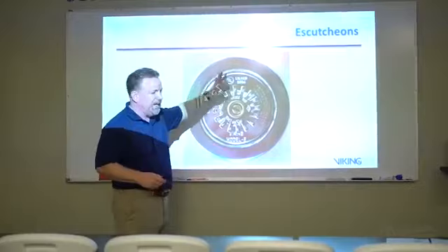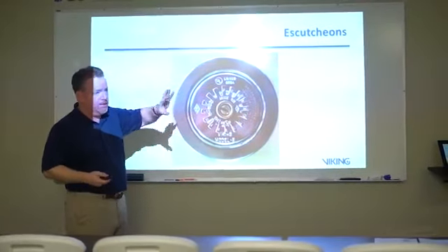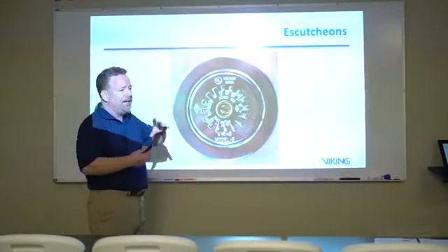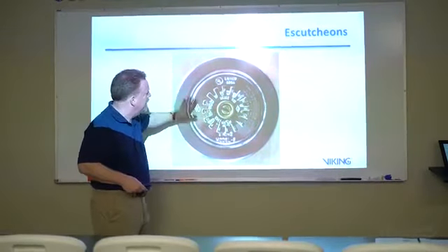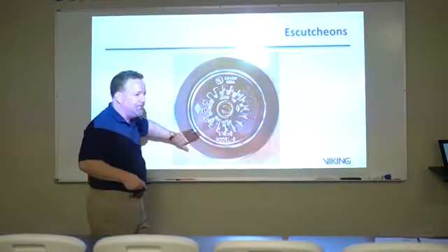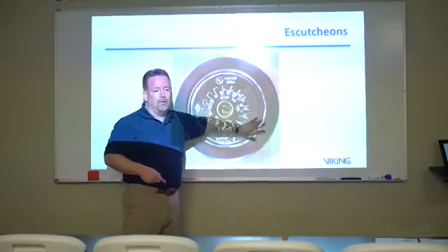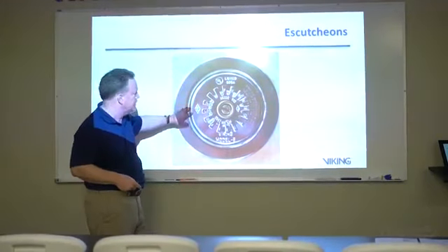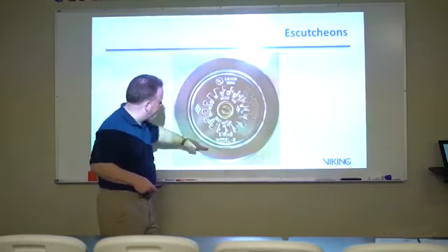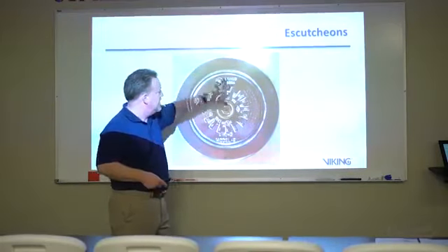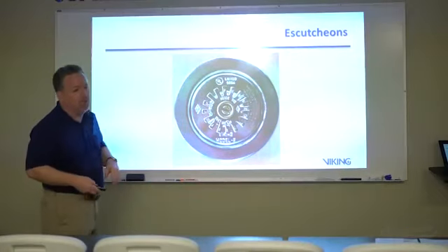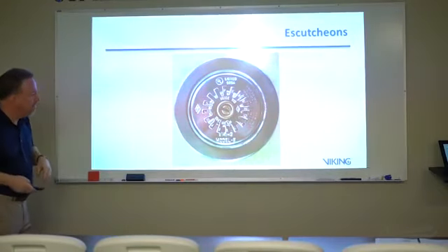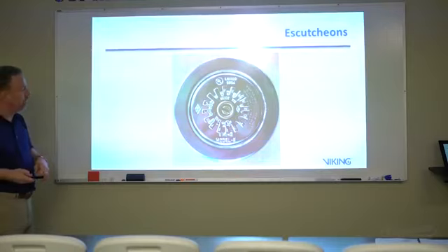So you can either have a listed concealed sprinkler that's totally hidden, or a recessed one that's just a little bit hidden, or a fully exposed sprinkler, but you have to make that hole look pretty. Nobody likes that thing ugly. So the escutcheon cup that goes around it is specifically used in conjunction with the sprinkler itself. So you have to build that all together.